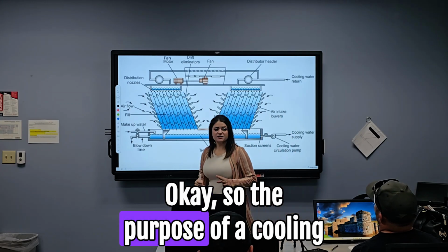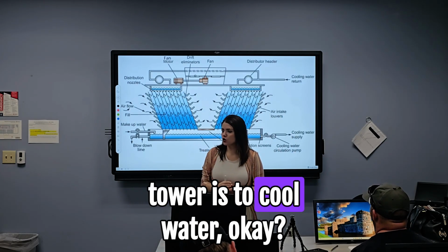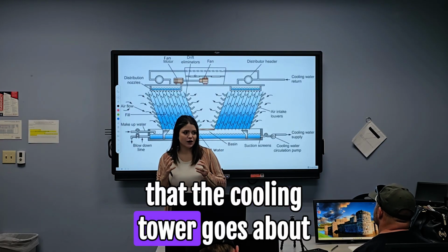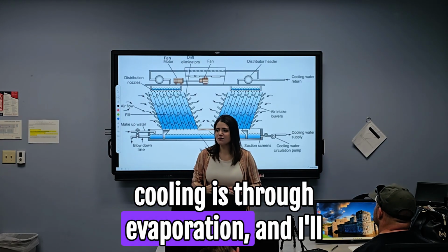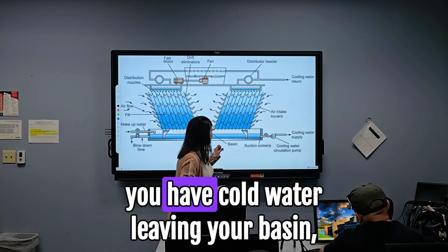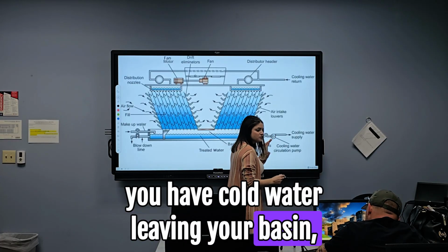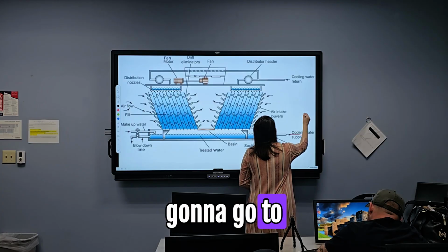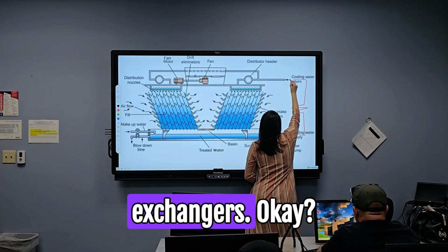Okay, so the purpose of a cooling tower is to cool water. The way that the cooling tower goes about cooling is through evaporation, and I'll explain more on that in a little bit. So you have cold water leaving your basin, going through your cooling water pump, and then it's going to go to all the different cooling water exchangers.